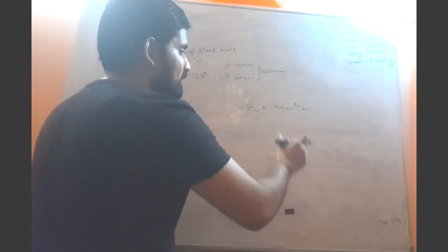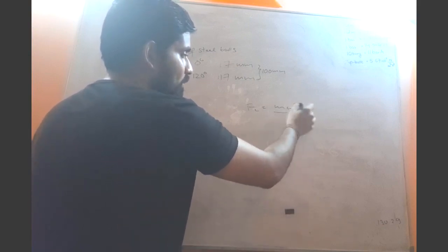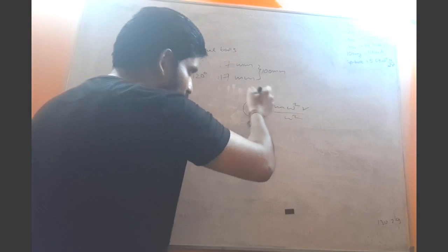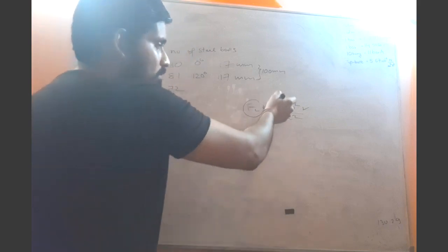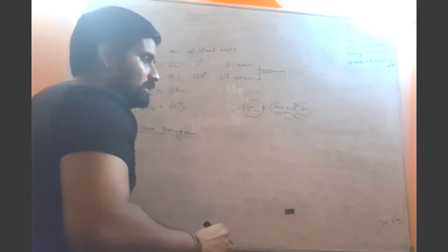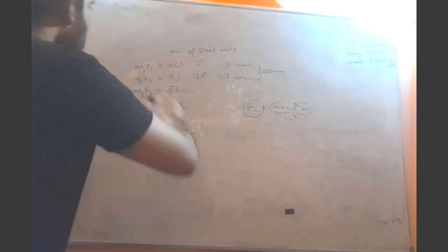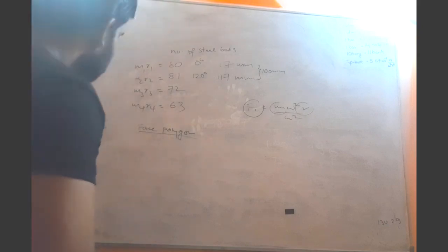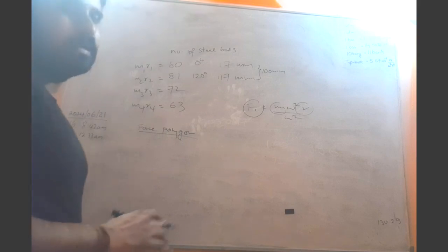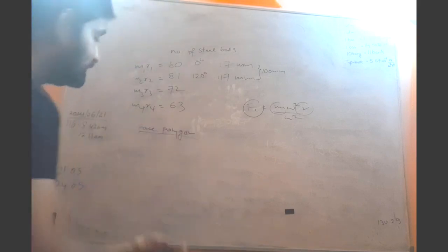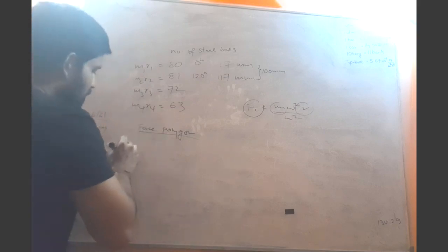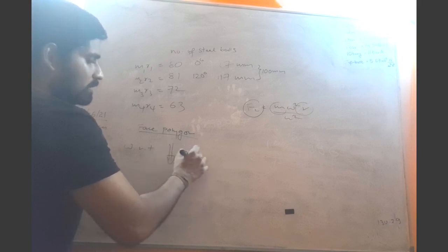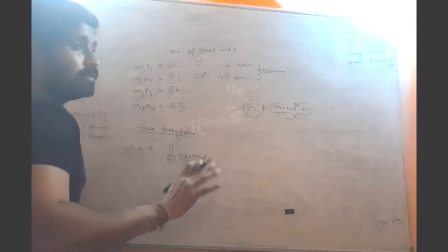But finally we divide this value by omega squared such that we obtain the centrifugal force in terms of the product of mass and the radius of rotation. That is what we refer to by m1r1, m2r2 and so on. Here the angles we are going to measure with respect to the downward vertical. Let's see how that happens.